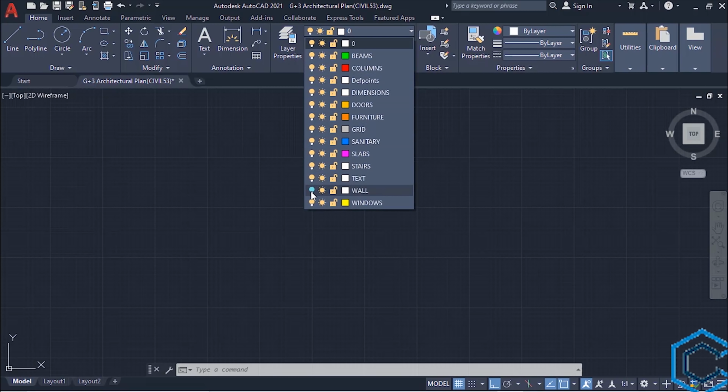So activate the line tool, L enter. So specify your first point, left click, and then give it a distance, give it a length of 2 and 3/8 inches, enter. Then go up, zoom in to make it clear. 2 and 2/8 inches, enter. And then we will give it half inch, 1/2 inch, enter.